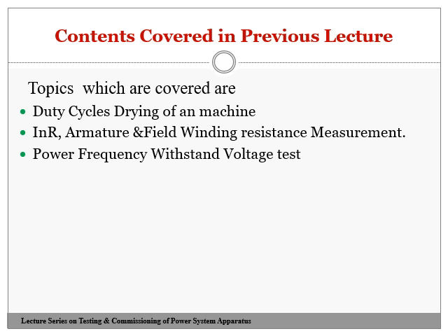Among the different methods, the common method we saw in the previous session is the short circuit method. Afterwards, we went on to measure the insulation resistance. There are many factors because of which the insulation resistance reduces. Once it reduces, we say it might have lost its insulating property, or the insulation is going to get deteriorated. Therefore, in order to maintain the specific value as per the standards, drying is essential.